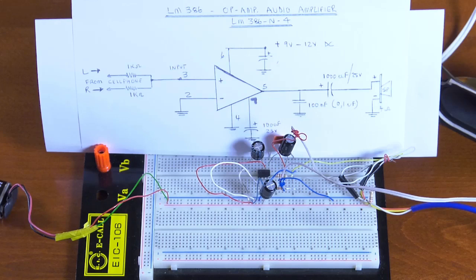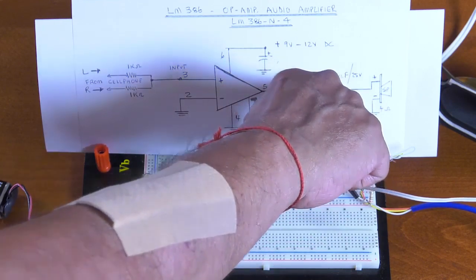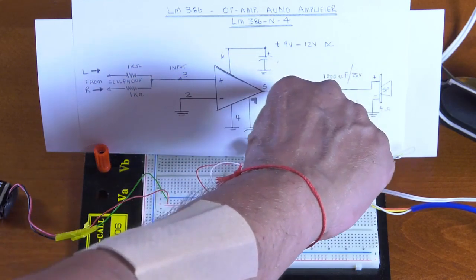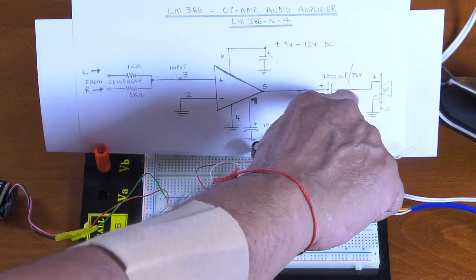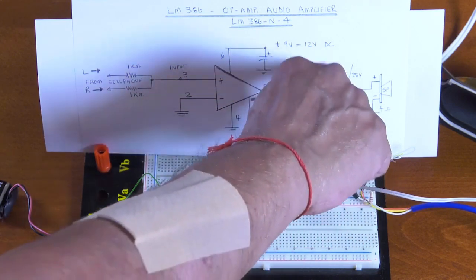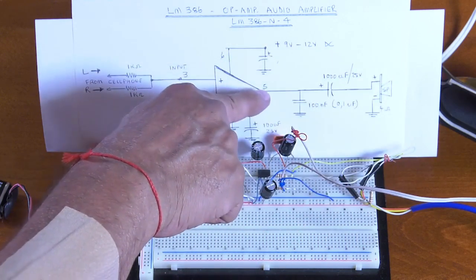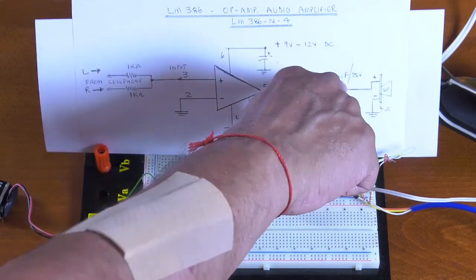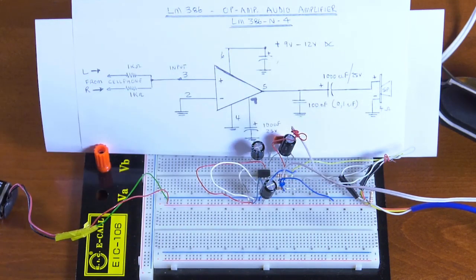There's a few things I'd like to point out here. First of all, notice that I've used quite a high value capacitor here at the output. You've learnt of RC coupling in amplifiers. You've learnt of transformer coupling. You've also learnt of direct coupling. This is a method of coupling the speaker with your output, which comes from pin 5. Notice also it's quite a high value. The reason for that is to get lovely bass sounds coming through to your speaker.